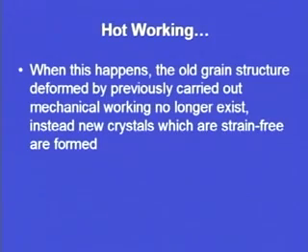So, whenever we raise the temperature above the recrystallization temperature, the old grain structure that has been deformed earlier will be removed, or will no longer exist, and new crystals will be formed, and these crystals will be strain free crystals.